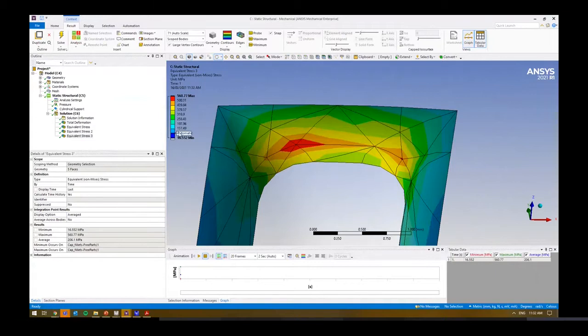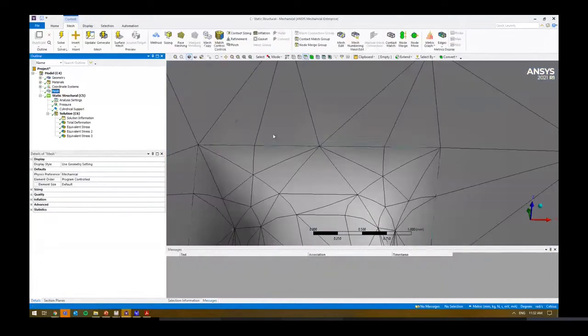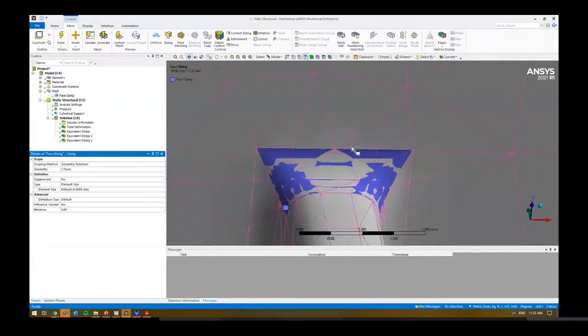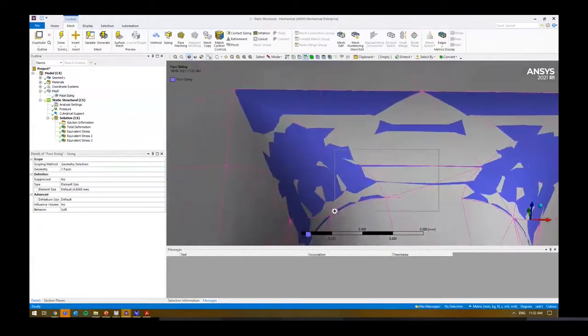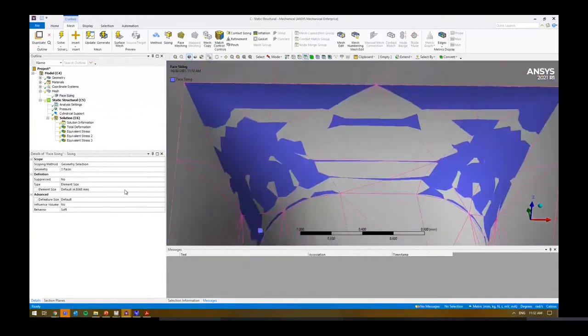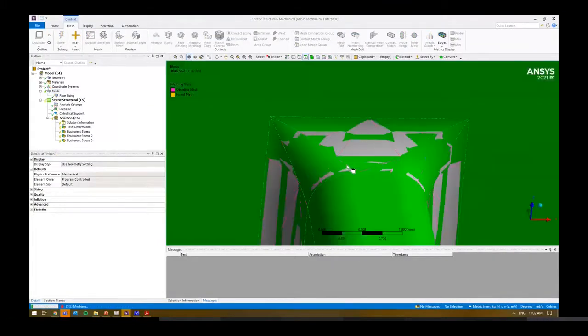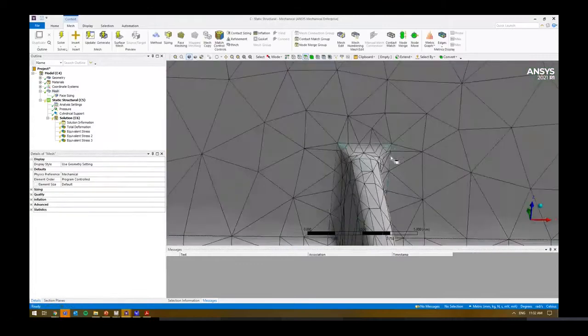So on the left, we've got a couple of axes here. Each one of these things is roughly a 10%. So I try to make sure we only have like one color band across the actual element, right? So let's just say we go in, we want to select these regions and we want to insert some sort of sizing, right? Maybe bringing this up, we want a sizing of say 0.5. Let's generate a mesh and let's see what happens locally around there, right?